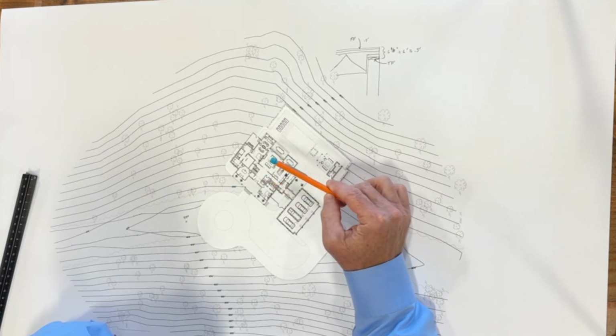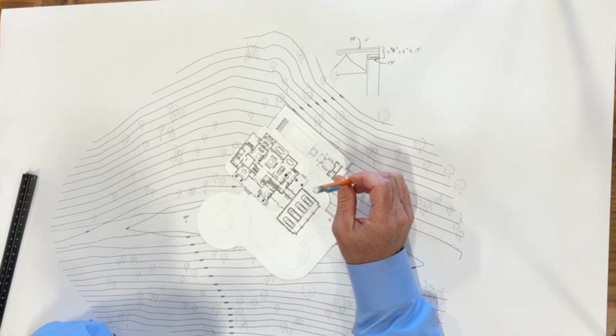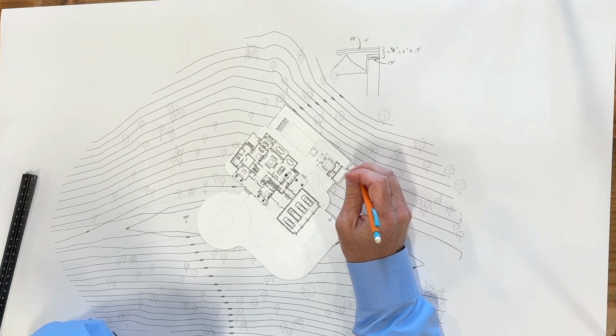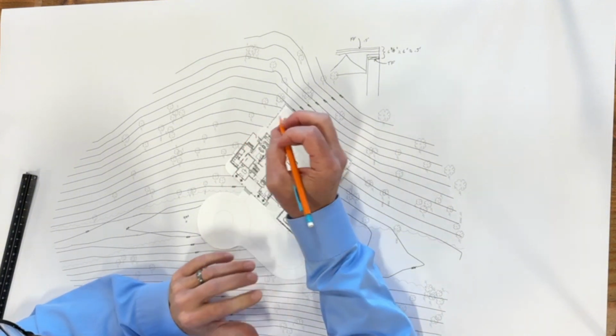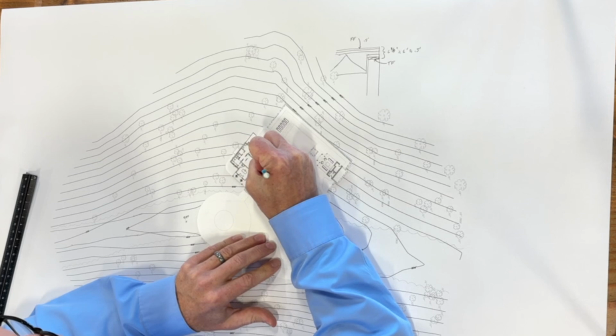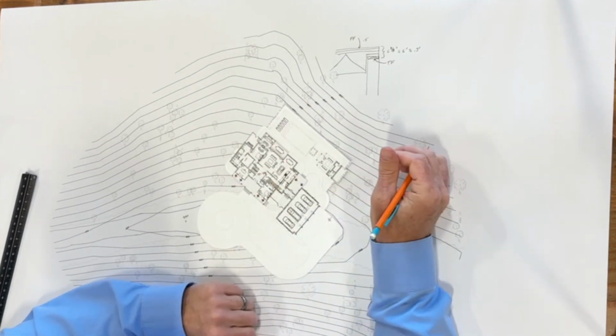So, you know, those two are out. A 2 or 3 foot rise from the pinnacle is probably a pretty good idea. So this could be, say, a 942, and it'd be 2 feet above that area. So I'm gonna just go with it, and then later on we can come back and change it. So that means the top of foundation is equal to a 942. Okay. Then that will set everything else.